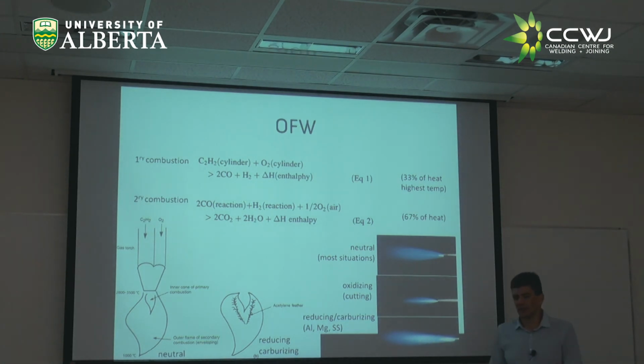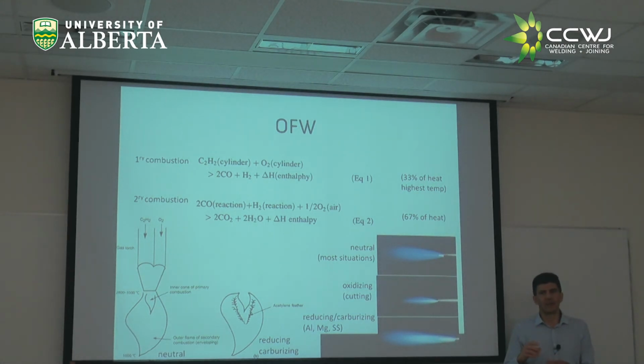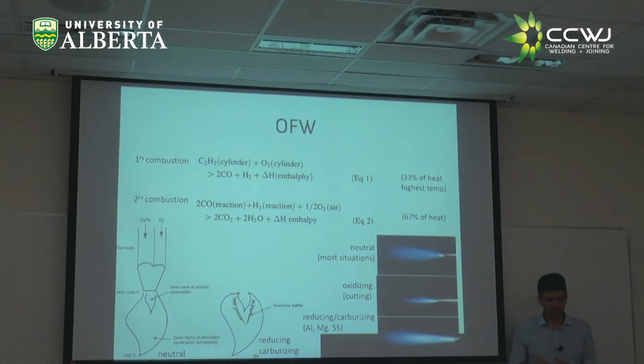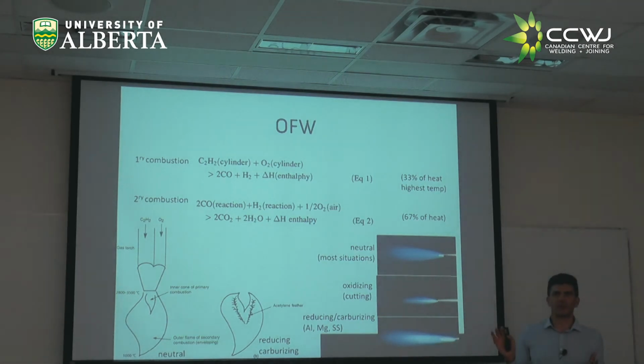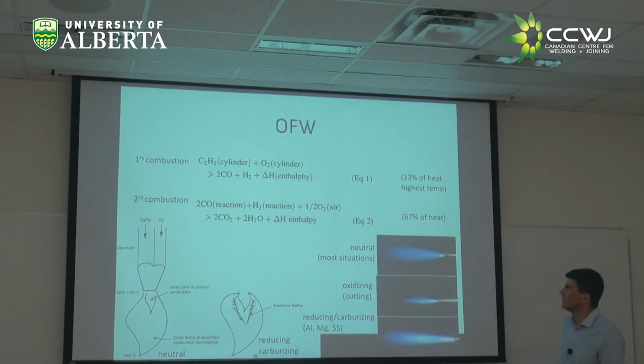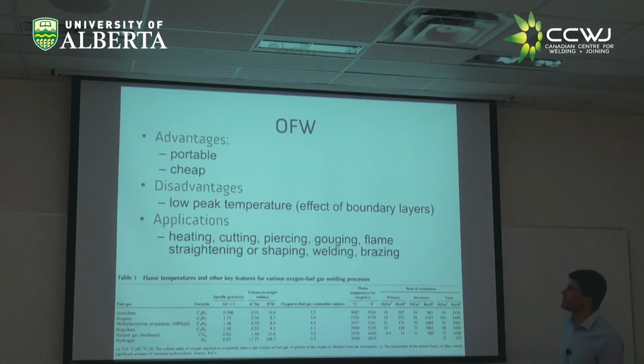On the other hand, you can increase the level of acetylene, right? You would have the inner core, the one with the acetylene, the first combustion, gets bigger. And the welders and the practitioners would look at the flame, would hear the type of sound that it makes. When you're reducing and the acetylene part is too big, it looks like a feather, right? That's what they call the acetylene feather. So this is how the chemical reactions give you this very intense heat.